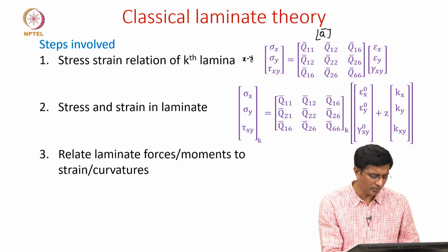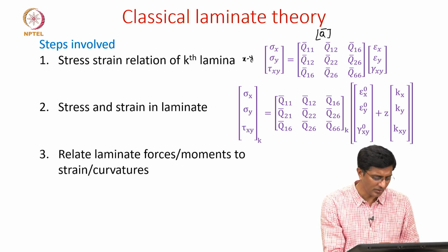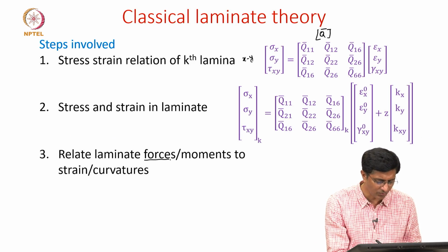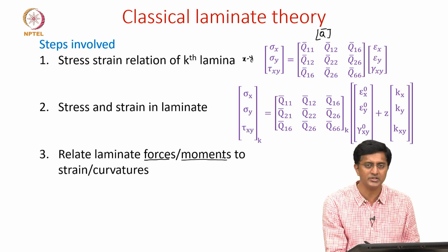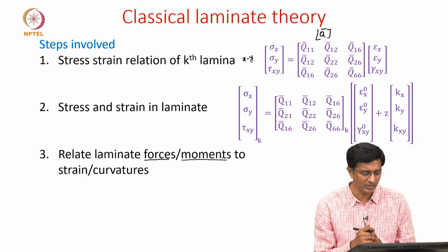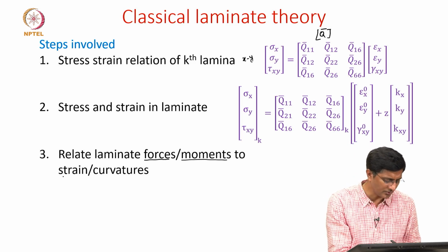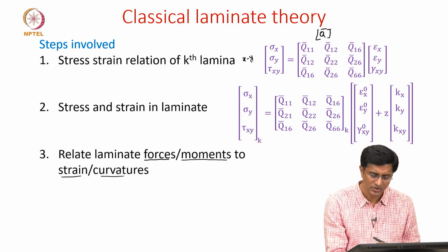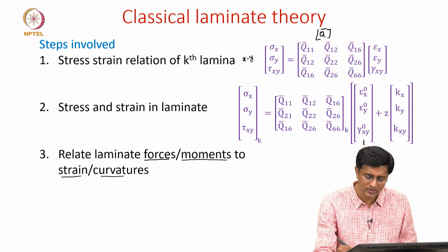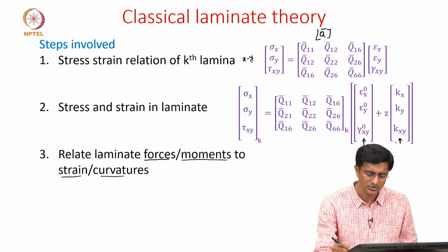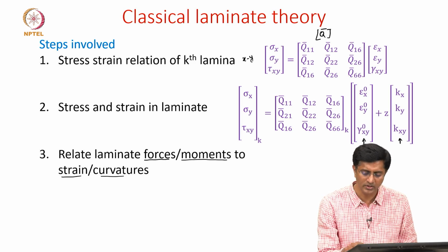So in this video, we'll be focusing on the last step, where we now start to discuss the forces and moments applied on this laminate. We'll write these in terms of the strains and curvatures which we have shown here. So these are the mid-plane strains and these are the curvatures. So we'll try to write these forces and moments in terms of the strains and curvatures.